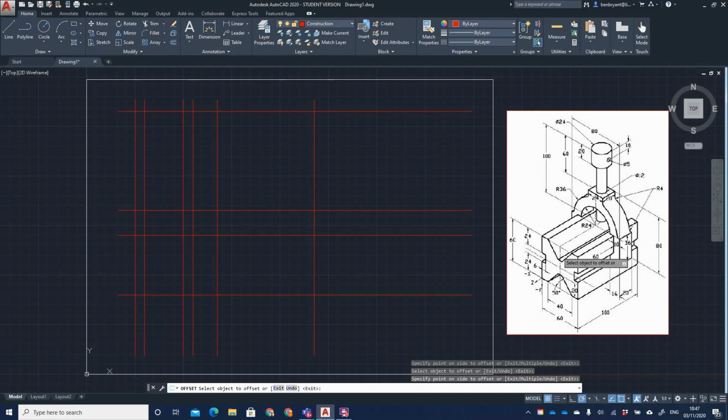I don't know any of the features for this V. I don't know the distance between because it isn't named. All I know is the V is 20 high by 50 mm on the diagonals. So what I need to do now is, on this front face, insert the V so I can map it up to my top view here. I know the V is 20 mm high, so I'm going to change the offset to 20 to give me my first line.